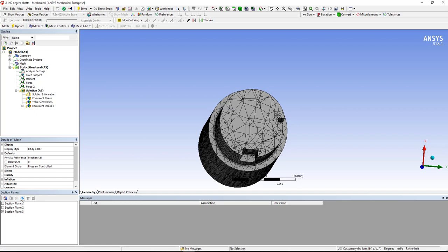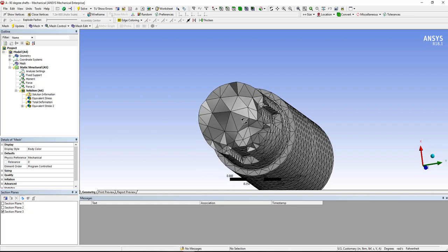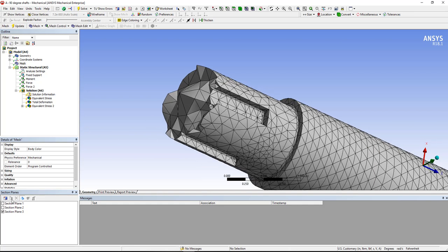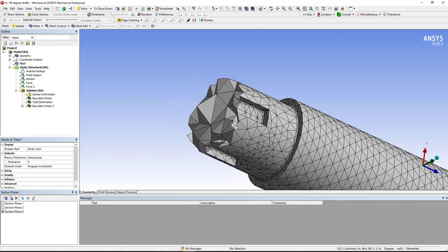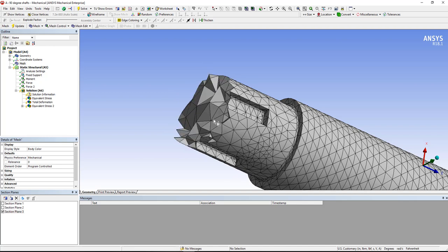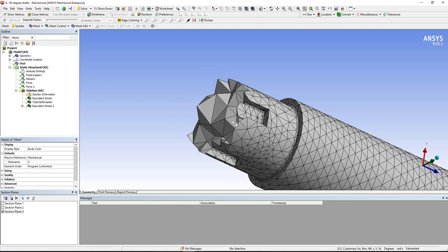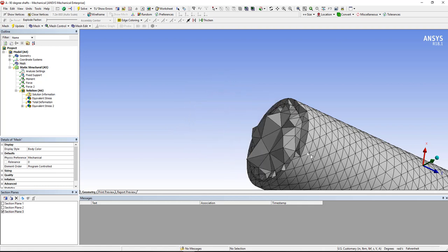But it's hard to see if you're just sectioning a little corner of an element or what the whole element is. And so you can turn on this function, which selects whole elements. And then we select the section plane. I can say edit section plane, and I get this cursor, I can drive it along. And so you can see that there's a fine tip to those elements, but I don't have a small element. They tend to be fairly large relative to the radius, and there's not ongoing refinement down into the mesh.